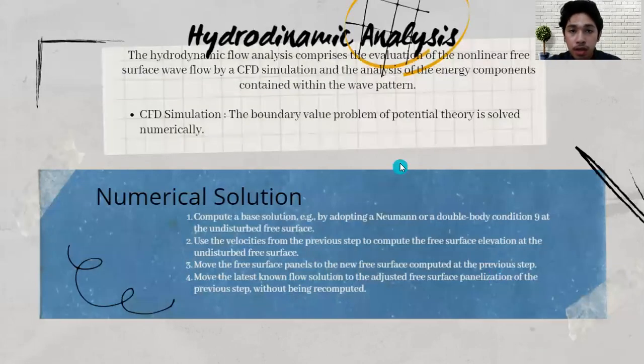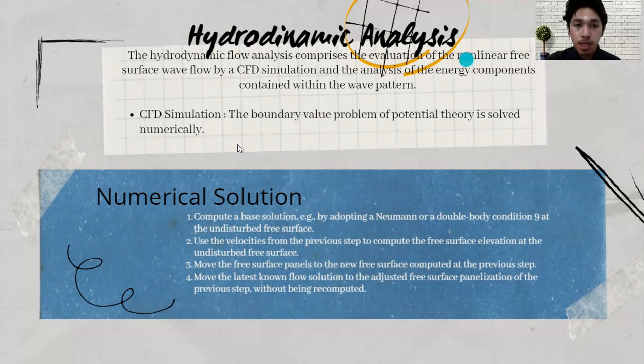So in hydrodynamic analysis, the flow analysis comprises the evaluation of the nonlinear free surface wave flow by a CFD simulation and the analysis of the energy components contained within the wave pattern. In this CFD simulation, the boundary value problem of potential theory is solved numerically.